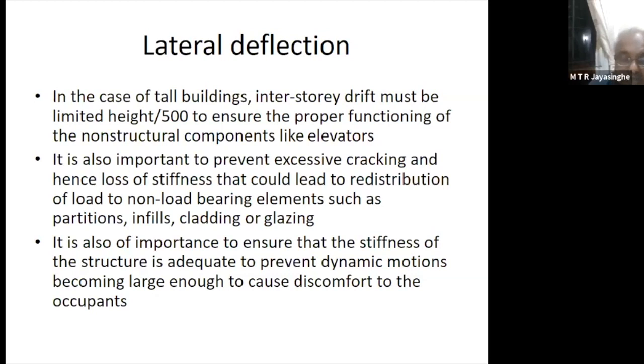That's a very important thing that you have to keep in mind, and now you can see why in all the super tall buildings that are designed today, concrete is becoming a very important material, and that is the number one choice. Why? Because the modern codes of practice like ACI code and Euro codes, they all allow us to use high strength concrete and make the maximum use of higher elastic modulus.